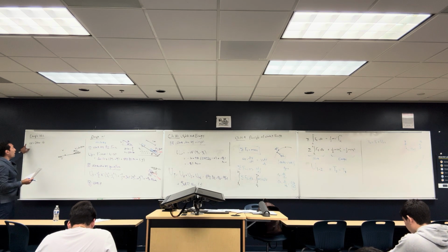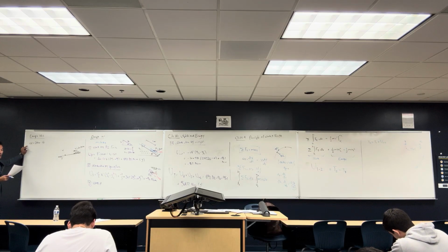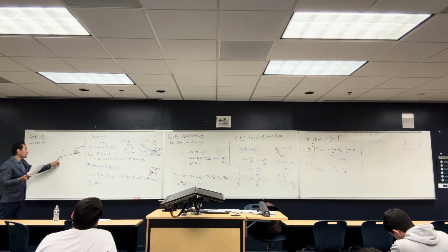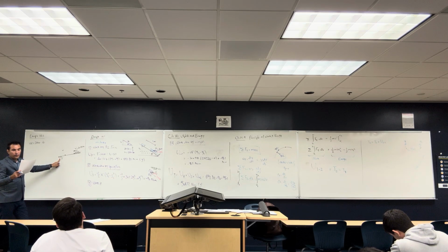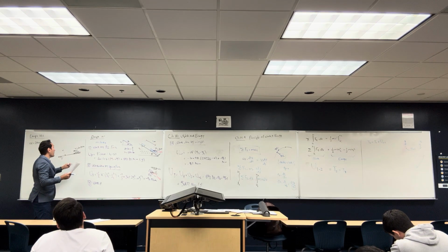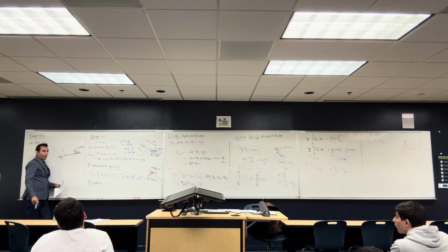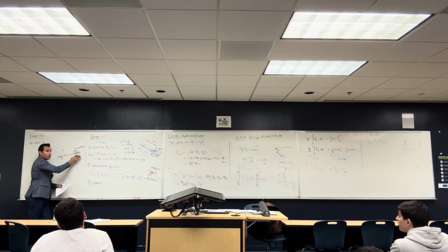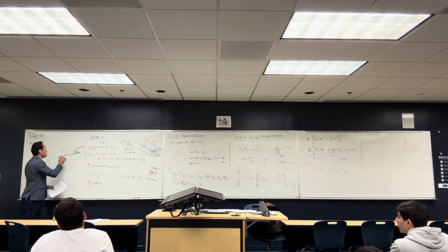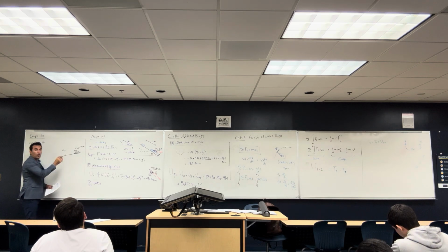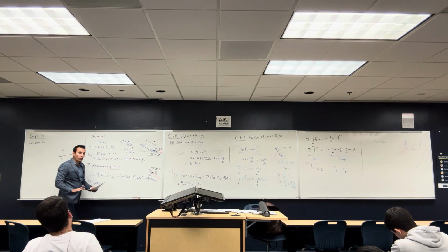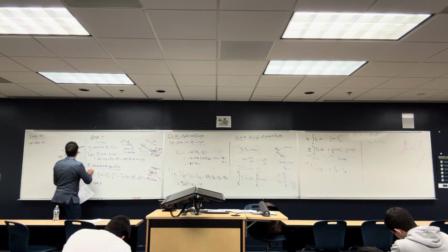We said that we have a car that is 3,500 pounds and travels down a 10-degree inclined road. If the driver jams on the brakes, causing his wheels to lock, determine how far the tires skid. Let me ask you, what is the initial velocity of this car? 20 feet per second, this is the initial velocity. Then you jammed on the brakes. What is your final velocity? Final velocity? 0, right? You jammed on the brakes until the car is stopped. So v2 is equal to 0.